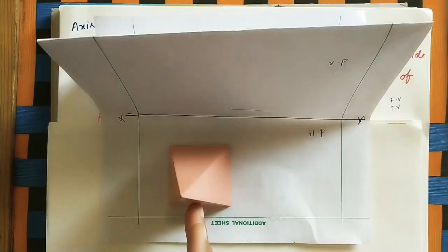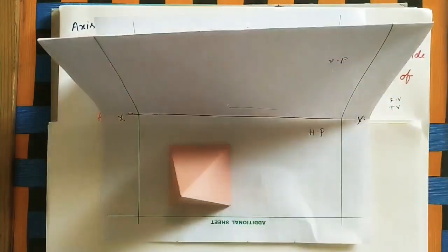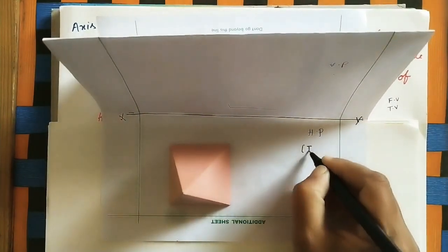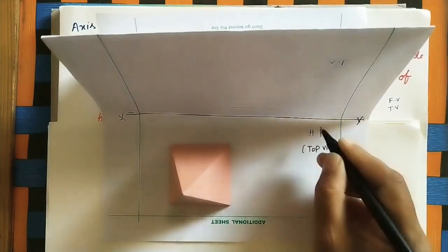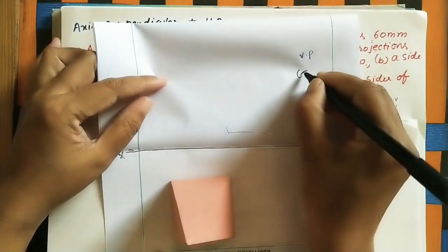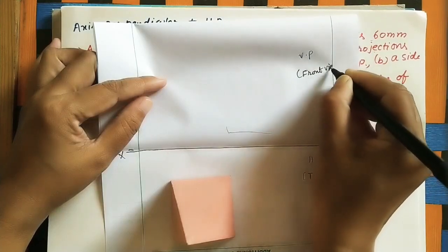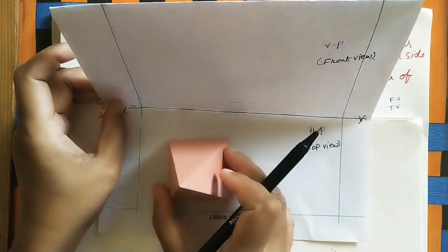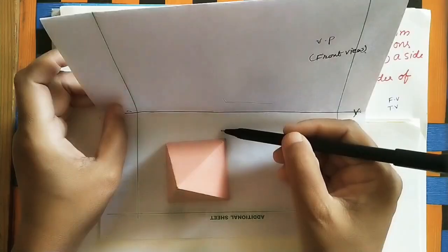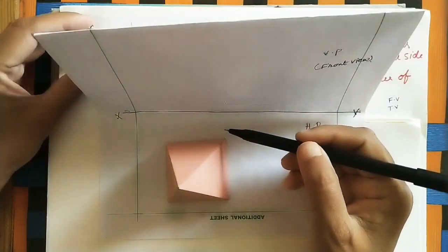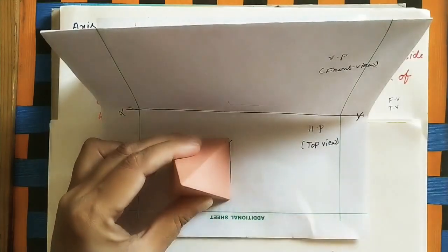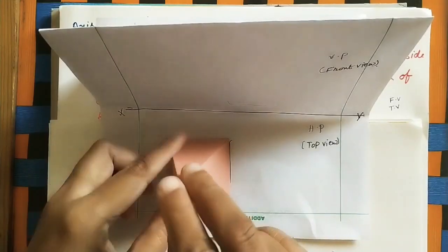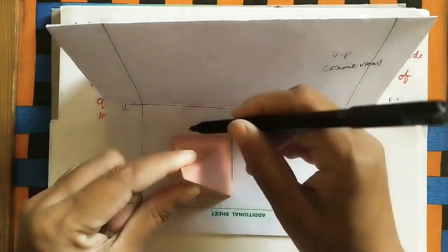Where can we see the front view? We can see the front view on the vertical plane. Where can we see the top view? We can see the top view in the horizontal plane. Right here we can see the top view in the horizontal plane, and the front view in the vertical plane. Now, from the first bit, one of the sides of the base is parallel to the VP like this. This gap is not given, so we can take any gap. So do the projections of it. For this, I will initially do the top view. If you see from the top, we can see this square base, and we can see the slant edges also. All slant edges are meeting at the center. First do the square.